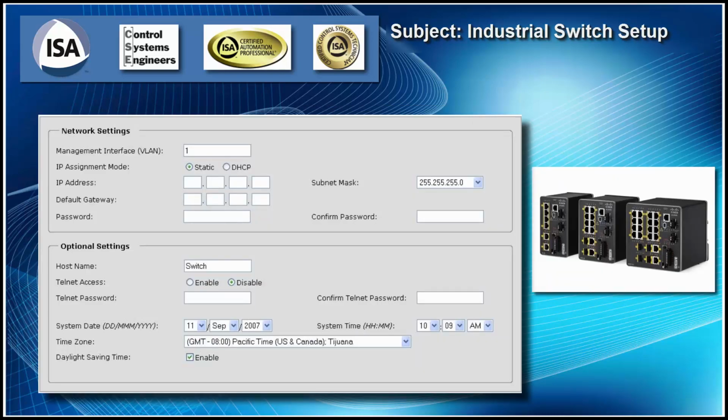Okay, when you're setting up these Cisco and Rockwell switches, the Stratix 5800, 5700s, and the IE 2000 and 3000s, never hit the express setup. It'll totally mess you up. It'll put in some kind of weird address like 204 dot something, and it won't work. What you do is get your laptop and a patch cable, and set your computer up for Dynamic Host Configuration Protocol. Then you press the button on the industrial switch. It has a DHCP server. Whichever port is flashing, that's the one you plug your patch cord into, typically port 1, and only the one flashing. Only when it's flashing do you plug in. Once you're plugged in, it turns solid green.